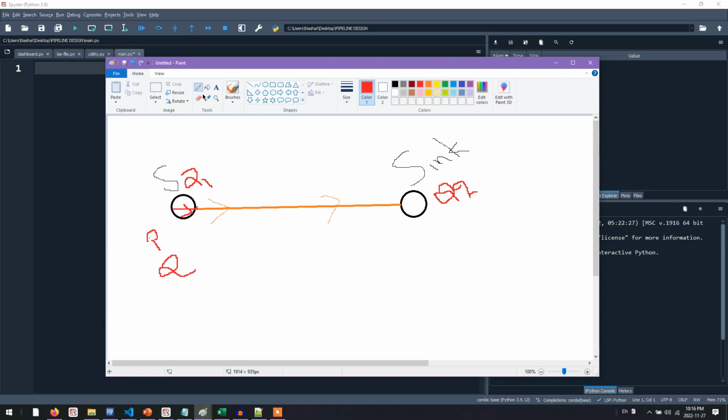And let's go back to the parameters in the source, and you have something called temperature. So those are the three basic inputs you usually use. And we have something else. It's actually the ambient temperature of the pipeline itself, meaning the air temperature around the pipeline. So these are all the basic information you need.